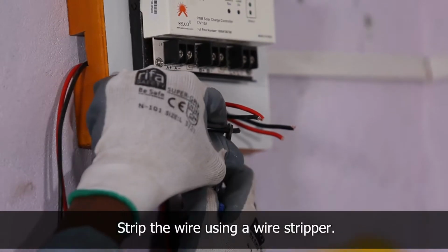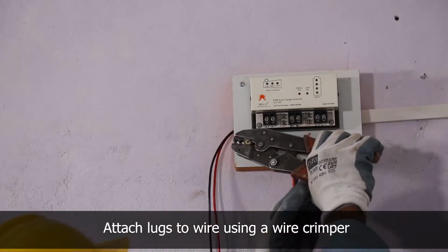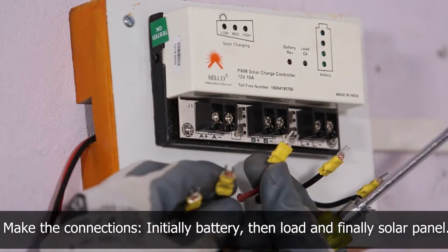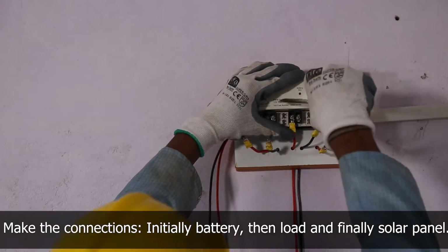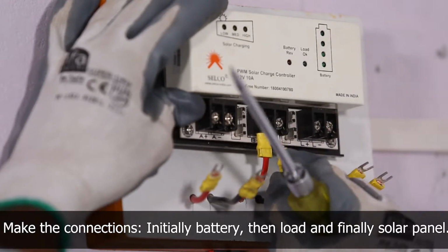Strip the wire using a wire stripper and attach the lugs using a wire crimper and connect it to the charge regulator. First, connect the battery wire to the charge regulator. Then connect the load wire to the charge regulator. And then finally connect the panel wire to the charge regulator.